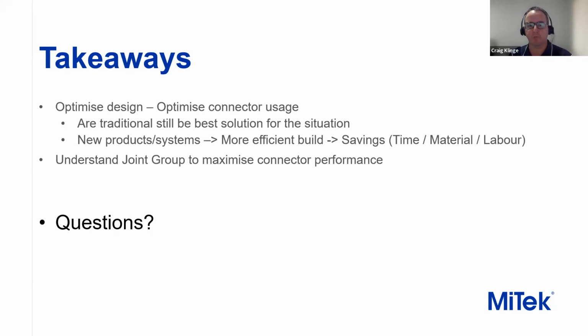So we do our own testing for the uplift capacities of the triple grip and the design of the nail spacings within it. But it would be important that whatever you're nailing into, you are meeting edge distances. So with a double top plate, just ensure that there's no nail trying to go through between the two laminations and things like that, which we do see occasionally.